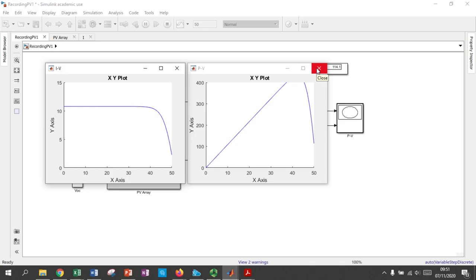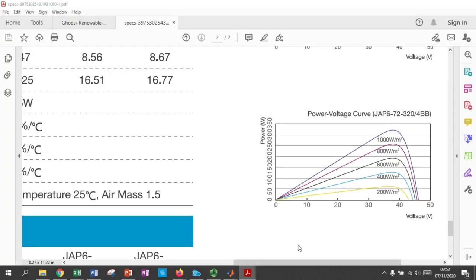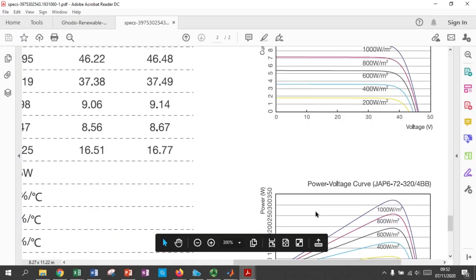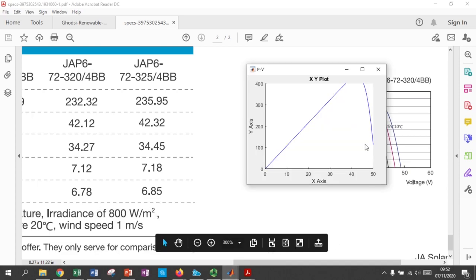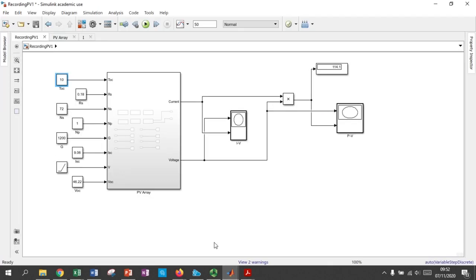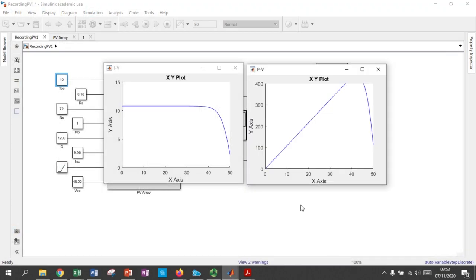Then lower temperature, as you can find here in the normal graph, I guess the effective temperature is not shown here. By decreasing the temperature, VOC will increase, and it was something that we can see. We should increase the boundary of the voltage VOC in our graphs.